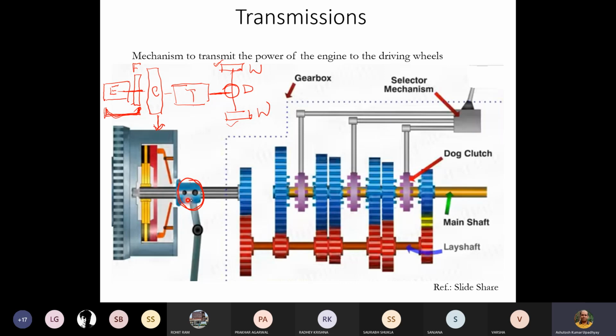It will basically push. If you see, we have got two components, and because of this pushing, this will be engaged or disengaged. Because of pushing, the friction clutches will be disengaged, and so they will not be in a condition to transmit the power. When you are running this transmission box, during that time this clutch will be completely engaged. All the friction components will be engaged together, and through friction they will be transmitting the power.